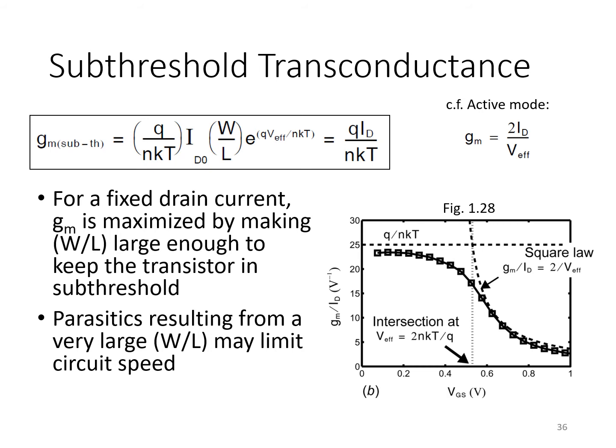So that's what we would expect purely from a square law. But in fact, that's not what you see. What you see is more like what's shown with the solid line here. As the gate source voltage approaches the threshold voltage, that is, as V effective approaches zero, it flattens out. And that's exactly what's predicted by the subthreshold current model that we presented on the last slide.